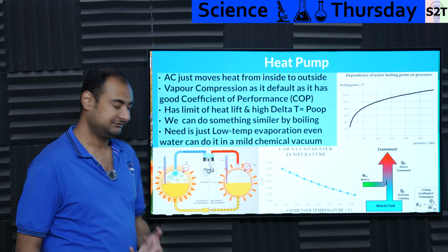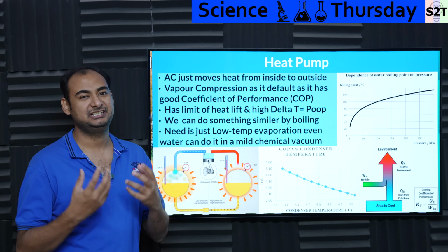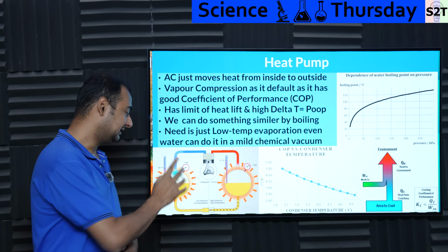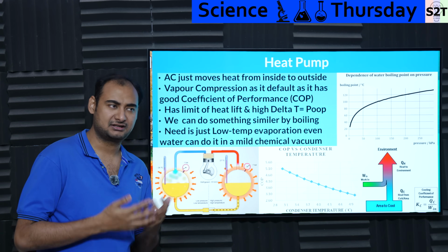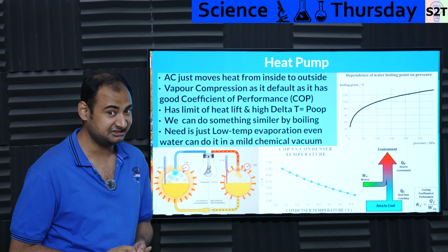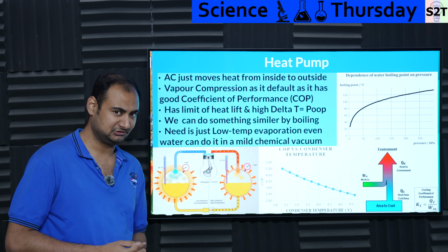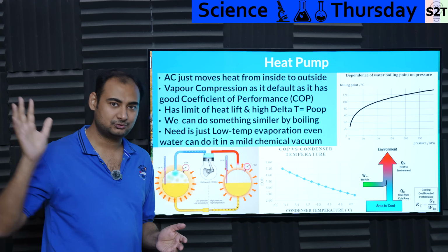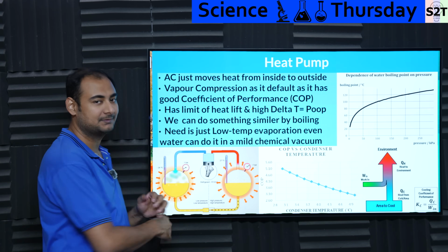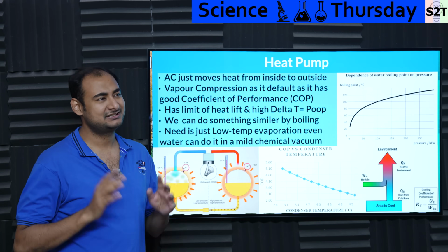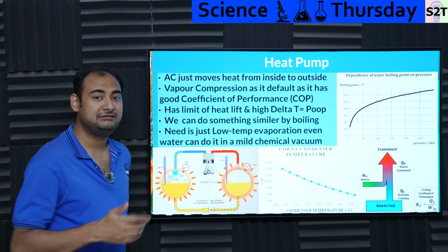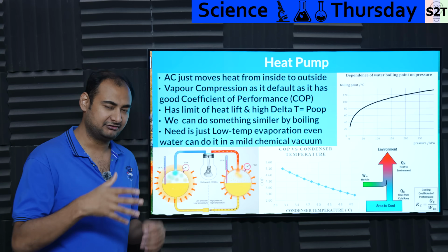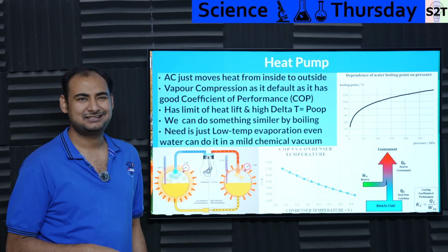And what are we seeking? We are seeking a liquid that boils at a very low temperature. Why? It does not need to be a very low temperature. While refrigerants we use in day-to-day life boil at like minus 18 degrees Celsius, minus 30 degrees Celsius, it's not necessary to go that low. Like, it helps with speed. The higher the T delta, the quicker the room heat boils this puppy, the quicker the flushing cycle happens. But it's not necessary. Especially if you are expecting to run the AC 24/7, the benefit of having that very low evaporative temperature does not really matter.